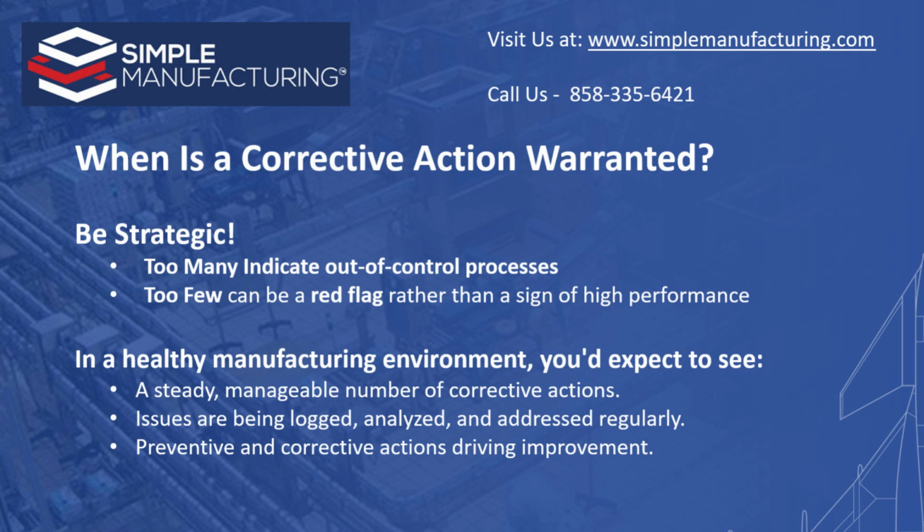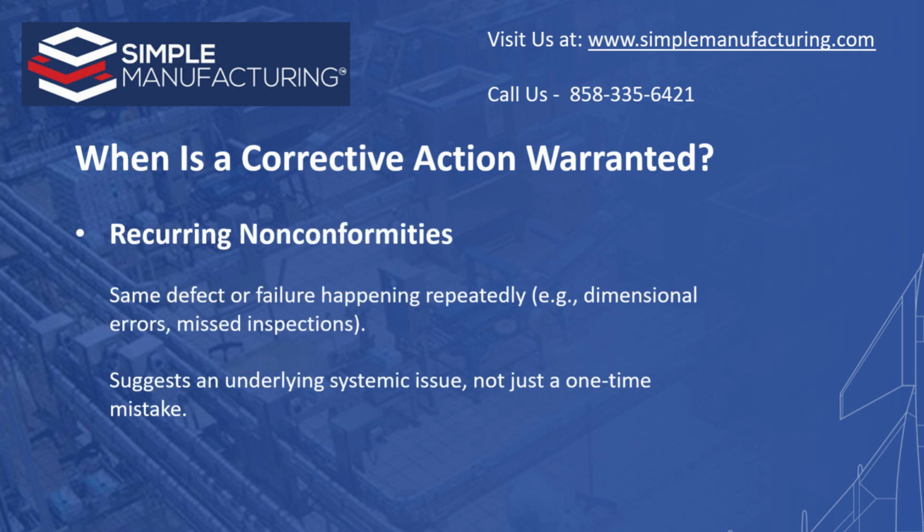Some advice for when to initiate a corrective action. First, when there are recurring nonconformities. Same defect or failure happening repeatedly, for example, dimensional errors, missed inspections. This suggests an underlying systemic issue, not just a one-time mistake.